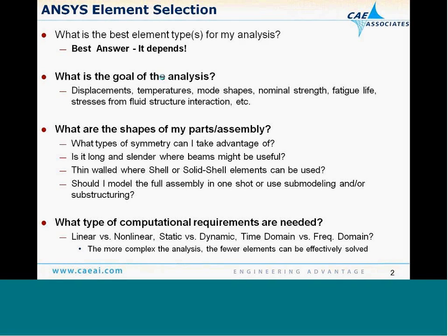If the analysis is a linear, elastic, static analysis, I may be able to afford to use a whole lot more elements. I just kind of mesh with all tetrahedral elements, whereas if I'm running a time history solution that's going to run for hours or days, or anything that doesn't run overnight, I'm going to spend a lot more effort getting the most efficient elements and element mesh for the particular problem in case.